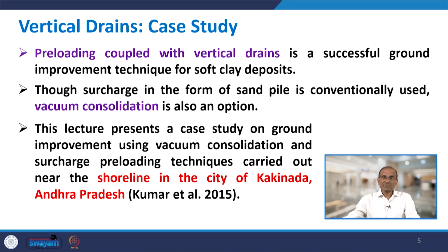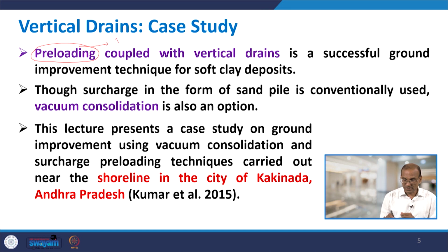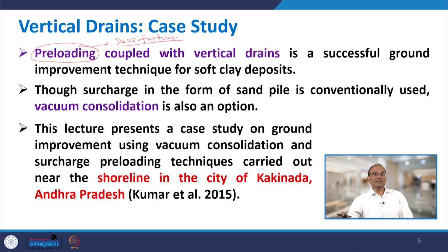For the case study, pre-loading coupled with vertical drains is a successful ground improvement technique for soft clay deposits. We already discussed in the last lecture that these vertical drains are mostly used for clay deposits. And if we couple preloading with vertical drains, preloading means basically densification. You are densifying the soil using some load. You couple this densification with vertical drains, then this combination is very successful.